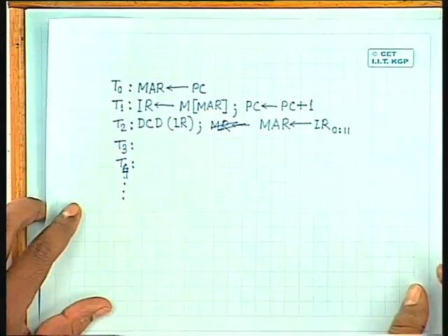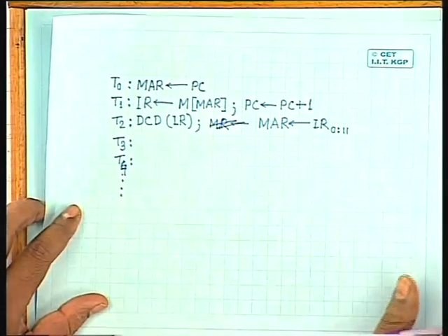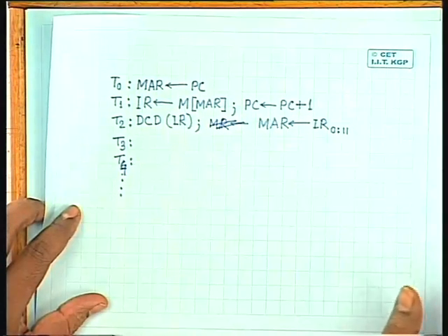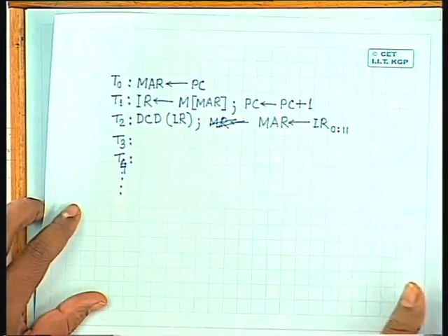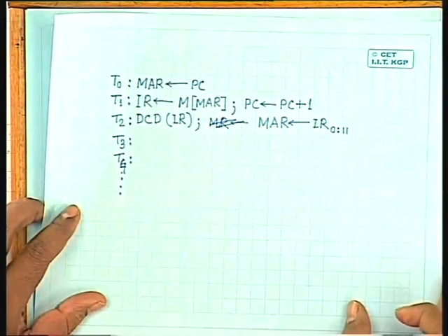Okay. So if in the 0th location in the main memory for an 8085 based system, I put anything other than an instruction, the instruction decoder will not give me any value. It will give me some garbage. And the timing and control circuit cannot recognize that, it cannot generate any proper timing control signal. Okay? Effectively, the system will fail.